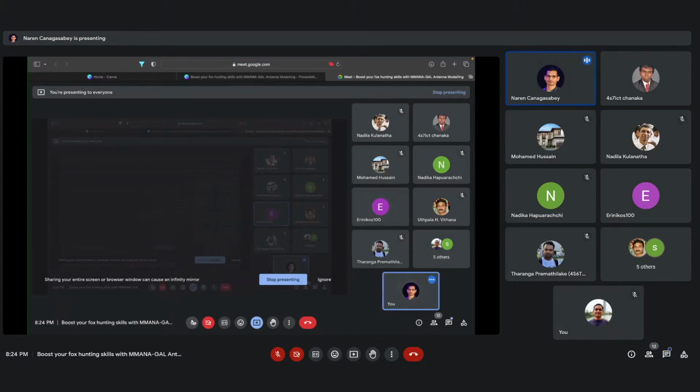I think for ease of construction, Ron, I might go with a Yagi, because it might be a bit difficult to bend the elements, if you know what I mean. But I would love to go with a Moxon, but say if you're using aluminum tubes, then it would be a bit complicated unless you have a bender.